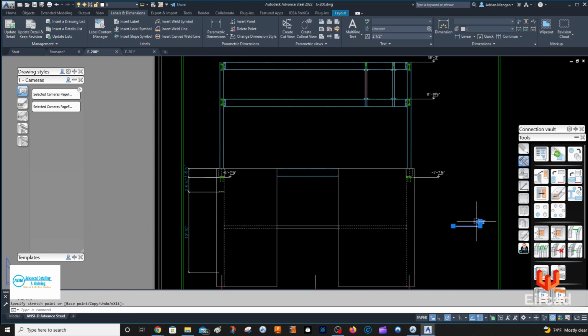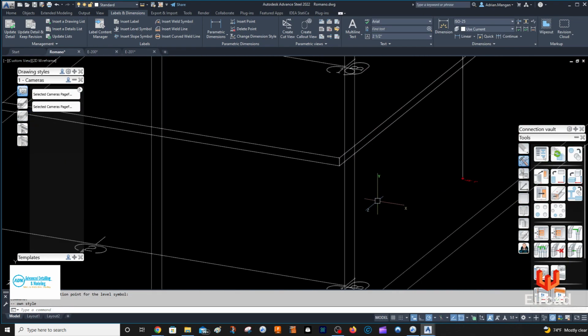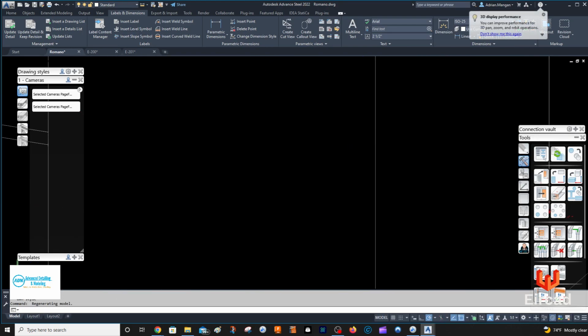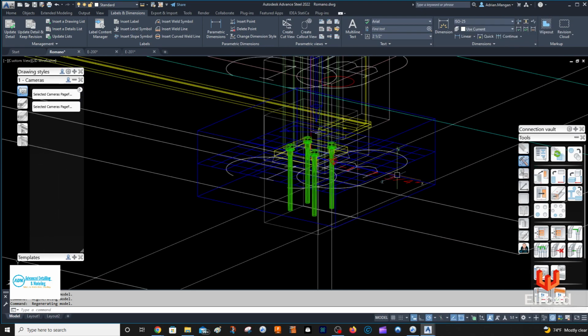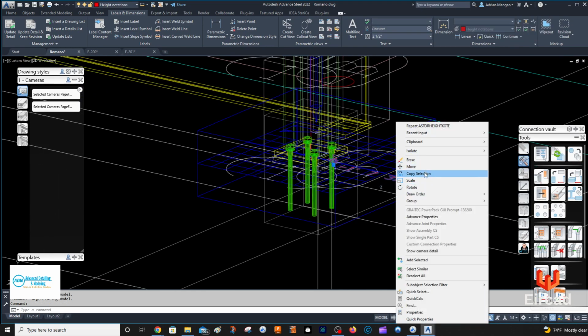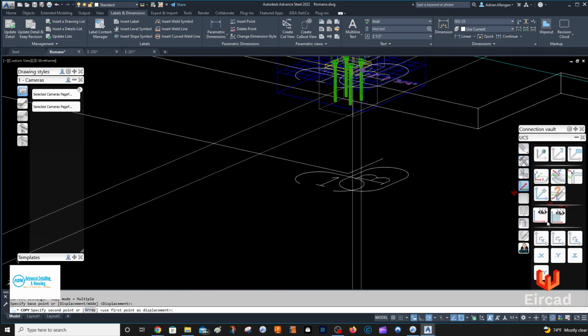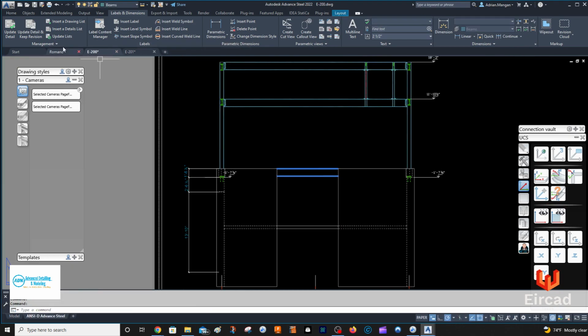This one here, I don't know what the story with this one here is. So let's go down and see if there is one down there, or I put that in manually, I bet. Alright, I put that in manually, I guess. So we want to put one in inside the camera. So what we'll do is we'll just copy this one. And we'll copy it down in the Y direction, as far as that slab, okay. Go back to 200, labels, update detail.